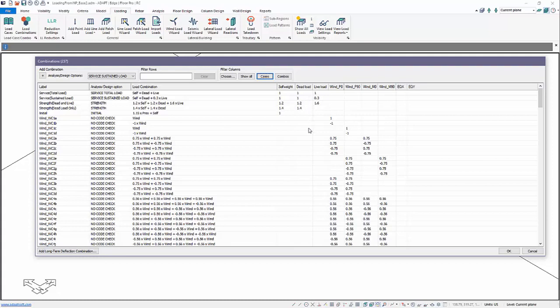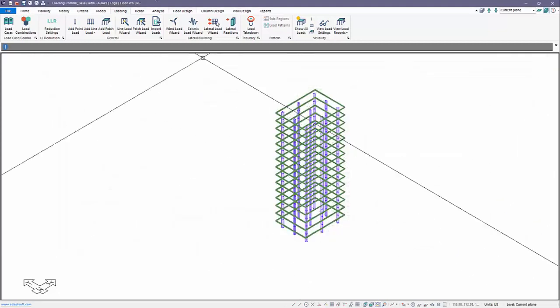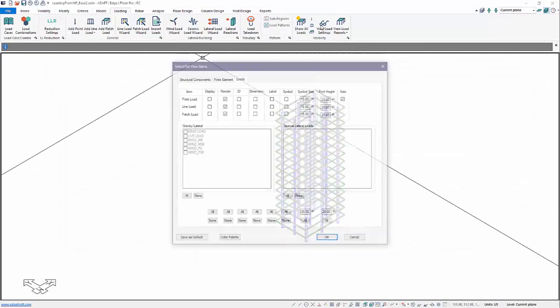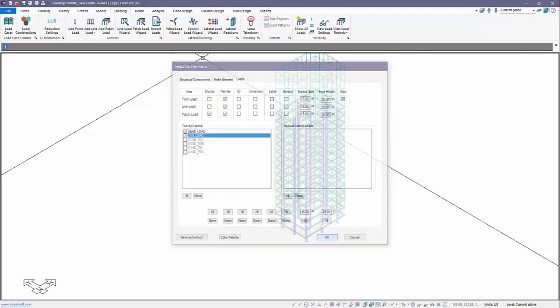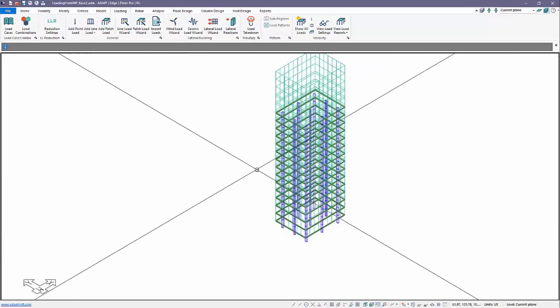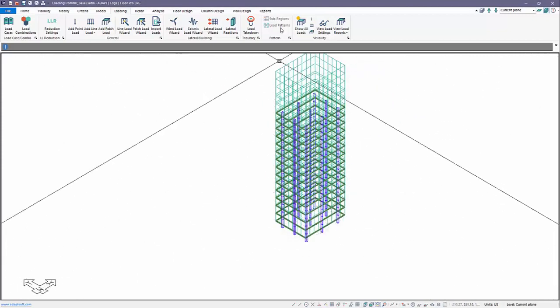You can write in the factors under dead load and live load, these two that are actually defined load cases. By defined, what I mean is if I go to the load settings, and go to patch load, I've defined loads as dead and live. Those were already assigned in this model.